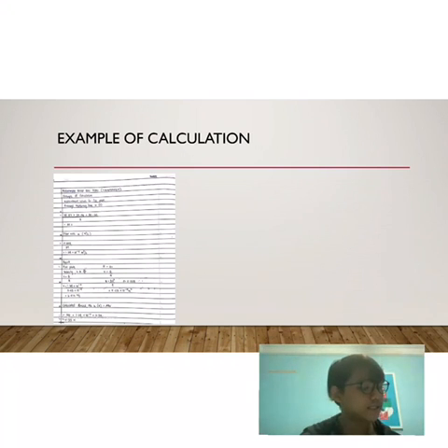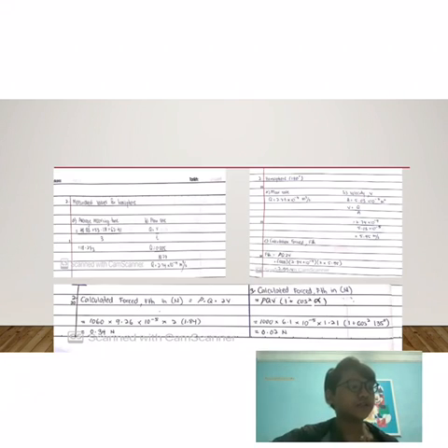And we can go through the velocity calculation: 1.28 times 10 power of -4 divided by 5.03 times 10 power of -5, equals 2.54 meters per second. Okay, and the calculated force, F in Newtons, equals 1000 times 1.28 times 10 power of -4 times 2.54, which equals 0.33 Newton. So next, I want to explain the calculation for measurement values for the hemisphere.